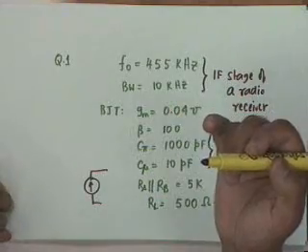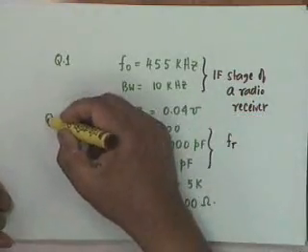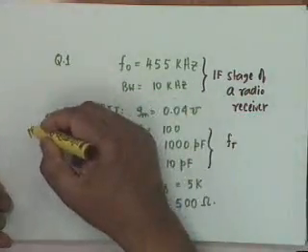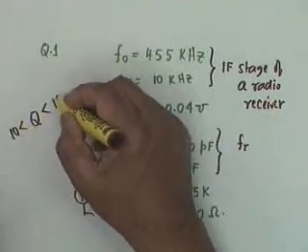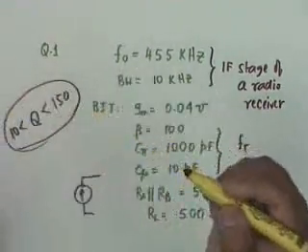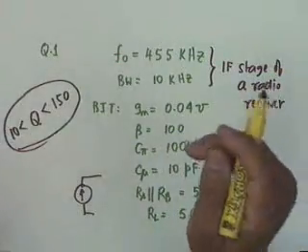In addition, as a matter of practical specification, it is stated that for a coil which is to resonate at 455 kilohertz, coils with Q between 10 and 150 are available, which means that you cannot assume the inductor to be perfect, which means that the inductor has a series resistance.